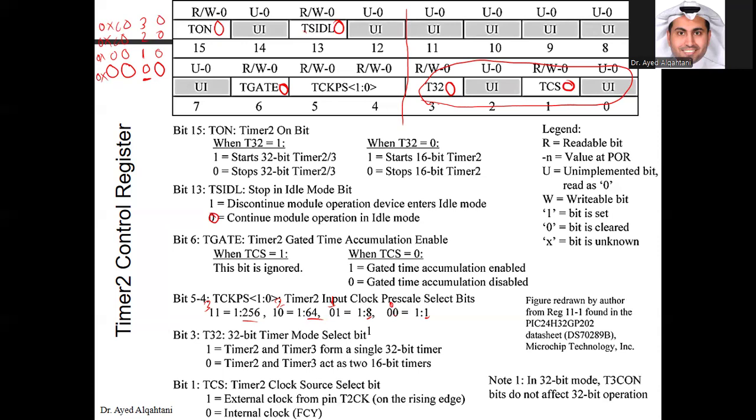These are the possible control register values, given that we choose an internal clock source, which is the obvious and the cheaper choice, and always given that we use only a 16-bit timer. So these are the 4 values based on the prescale selection bit.